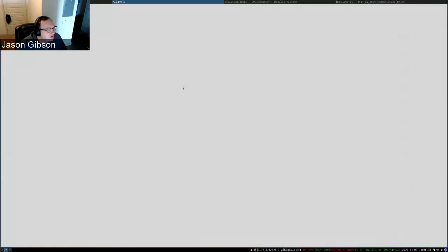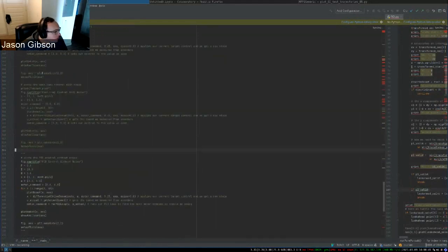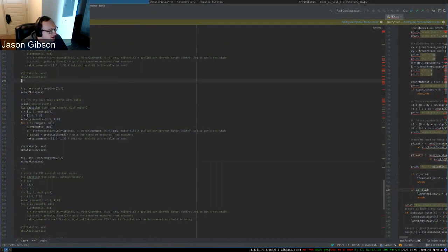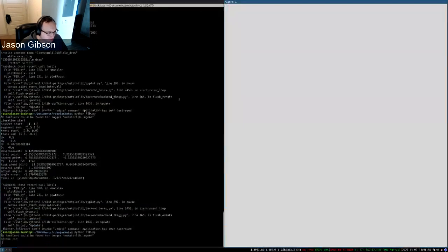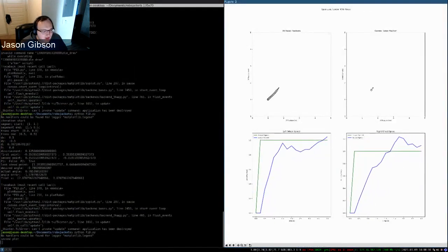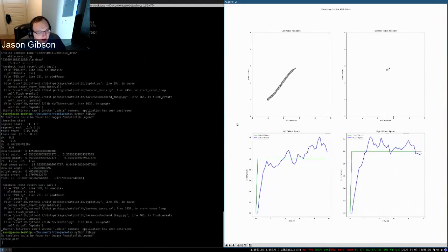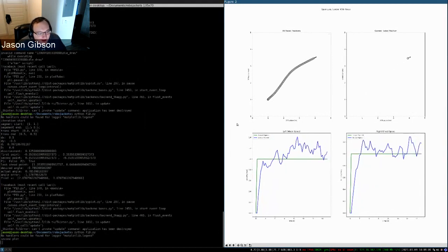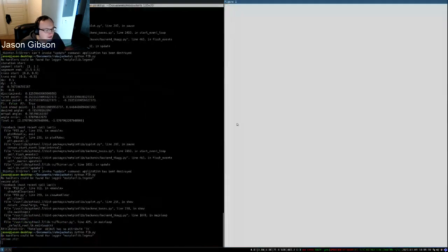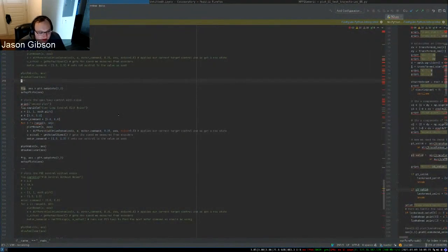Now I will rerun the one with open loop control. What you're going to see is we run open loop control with noise. This is us trying to just do direct force application. This is what you guys are probably doing now, with just setting the actual motor voltage. You can see how we kind of curve off into a different direction. And remember, the noise between these two is exactly the same. Of course, it's going to be weird about the bottom now. But remember how from that PID control earlier we were actually keeping within.